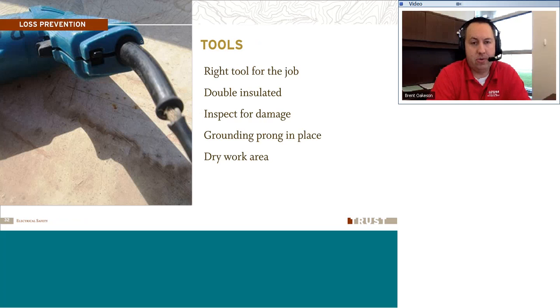When it comes to power tools, a lot of hazards happen with this. People get into trouble with getting exposed to different wires and things getting torn in the insulation on the wiring and things getting exposed, and they get shocked from it. So make sure that you're checking your tools out, whether it's a drill or a saw or any other type of equipment that has a cord on it. Check that tool and that cord for any damage. Here you can see there's some strain going on the cord. You can see that it's being pulled away from the equipment and obviously could cause damage and open up the wires there.